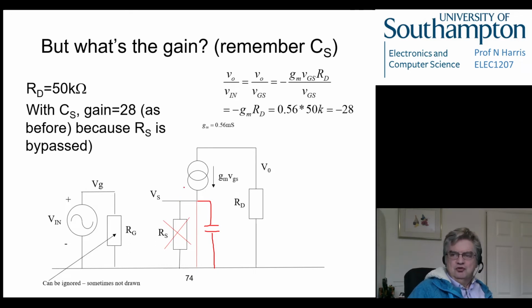So here's a capacitor looking like a short circuit, and we've actually got the equivalent of a wire bypassing this source resistor. Any current in this part of the circuit will want to go through that wire and not through the resistor. It's like an extreme current divider. So we bypassed it because at high frequencies this is a short circuit.